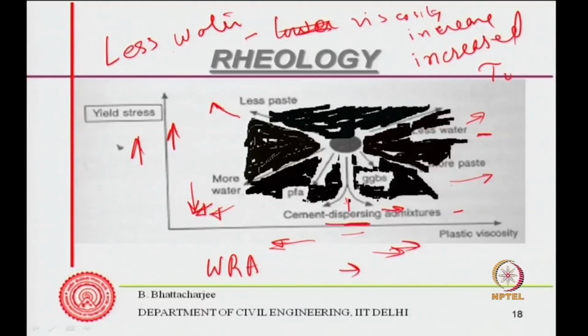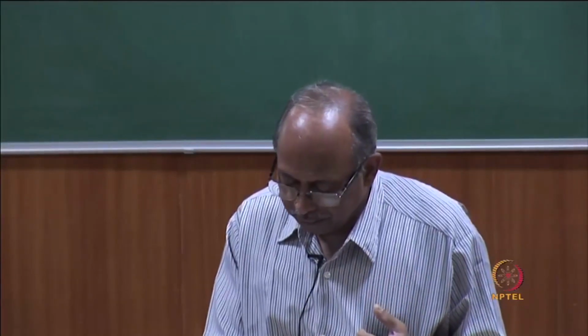More paste causes the plastic viscosity to increase, and the yield shear stress decreases, moving along this direction. We can also see that if we add pulverized fly ash or GGBFS, it reduces the yield shear stress and also the viscosity.